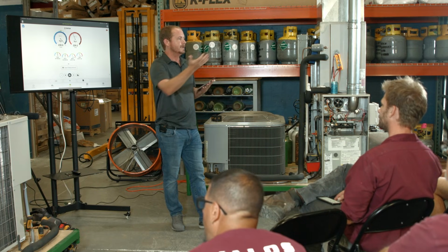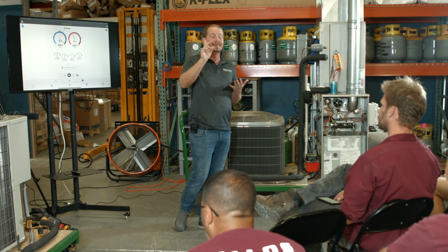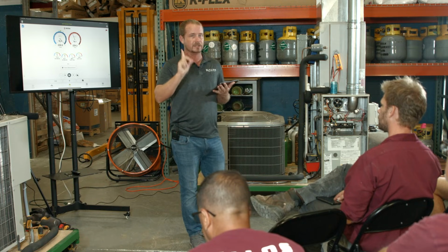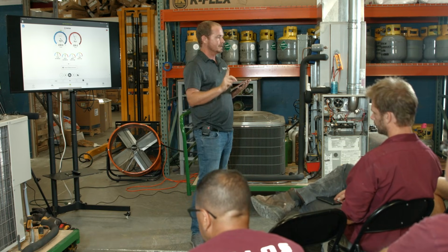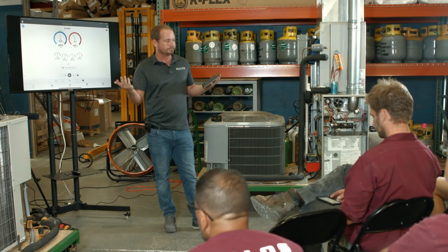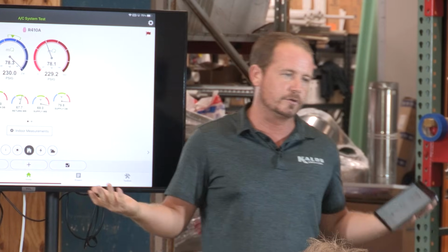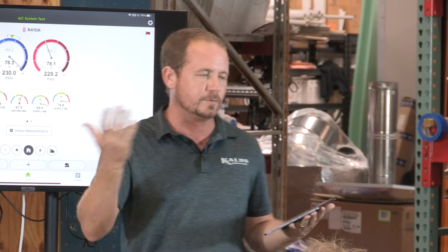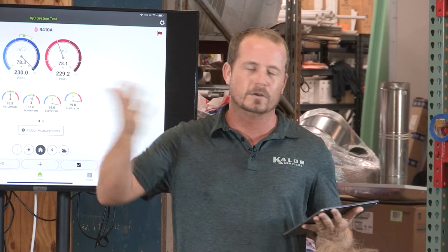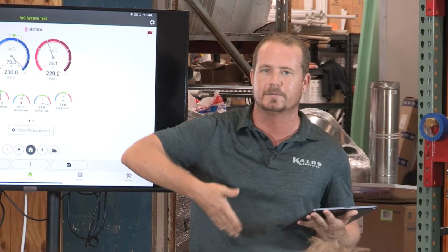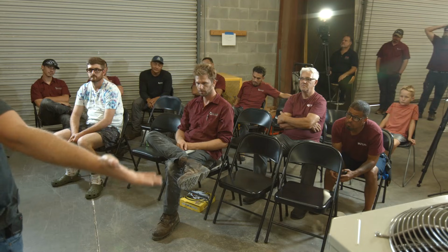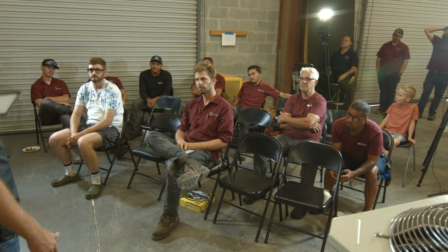It's light gas, and that's actually going to cause the compressor to overheat, even if the temperature of it is low. This is a tricky business because guys will say, "Well, look, my return gas temperature is 45 degrees. You told me that it's the refrigerant that cools the compressor, and you also told me that low airflow causes lower suction gas temperature. So why doesn't this lower temperature gas cool the compressor better? Wouldn't it cool it better? It's colder." The answer is no, it doesn't, because there's less of it, because it's light.